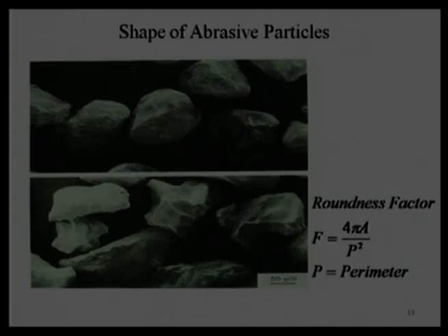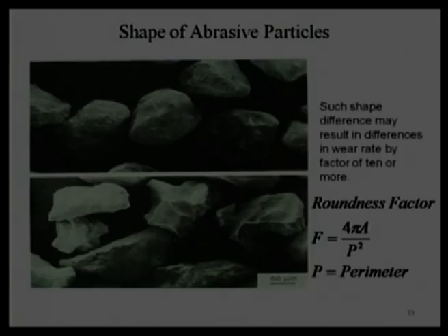Three body abrasion is lower compared to irregular particles, and that is the reason many times we use particles for lubrication, and particle shape is kept as a spherical shape, which is not going to cause any failure, which is not going to cause abrasion of the surface. That will always be advisable. Choose particle shape in such a manner which causes lesser abrasion.